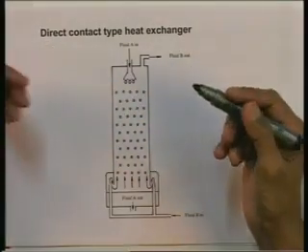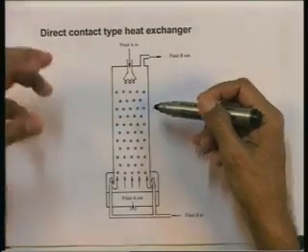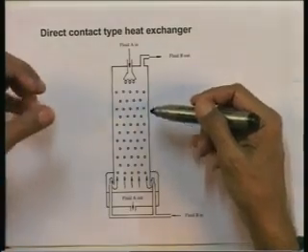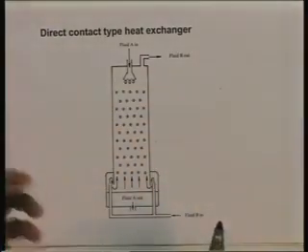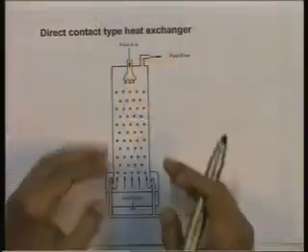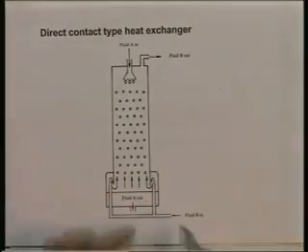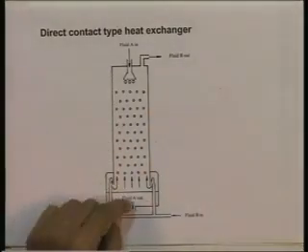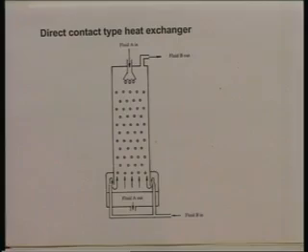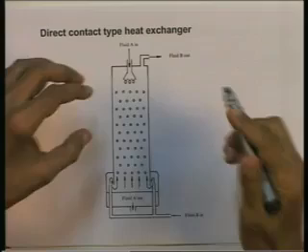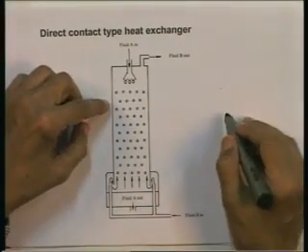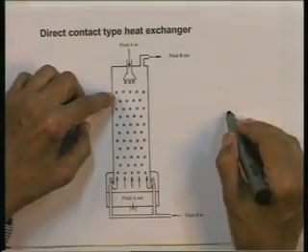All right. So, this is what we call a direct contact type heat exchanger, in which one of the fluids is deformed. Deformed means put into the shape of, say, droplets or bubbles, and then the heat transfer takes place. After the heat transfer takes place, it is all collected and flows out. So, the droplets all get collected here and flow out. That is why we call it a direct contact type heat exchanger, because the process of heat transfer here occurs in this case at each drop.